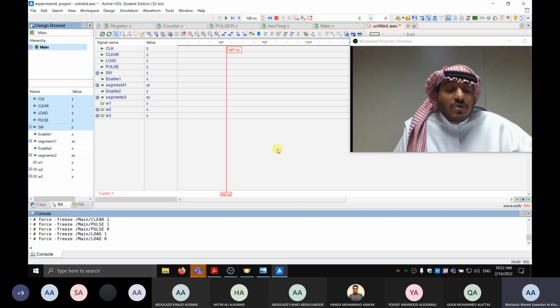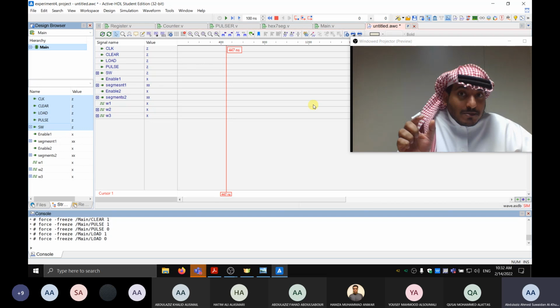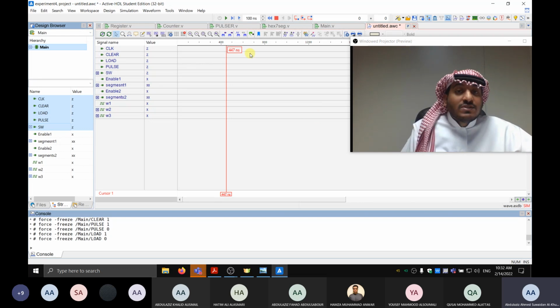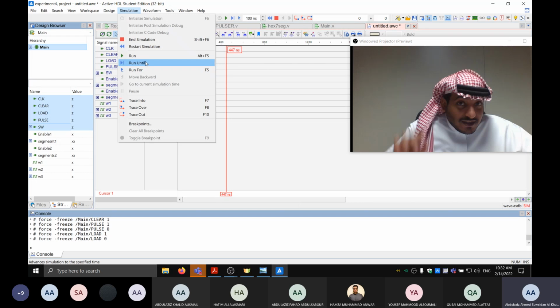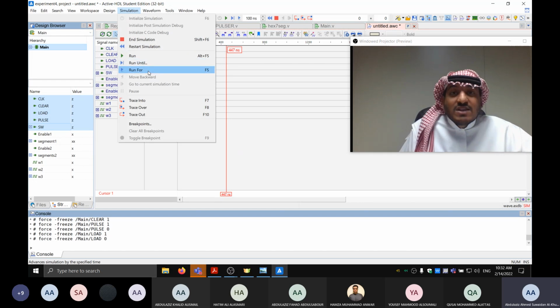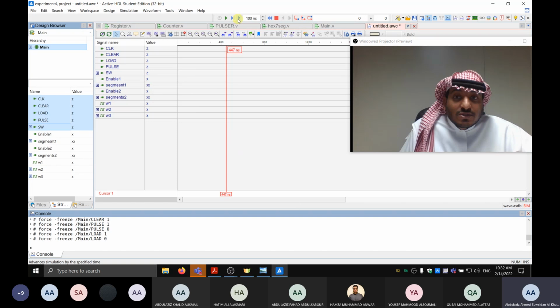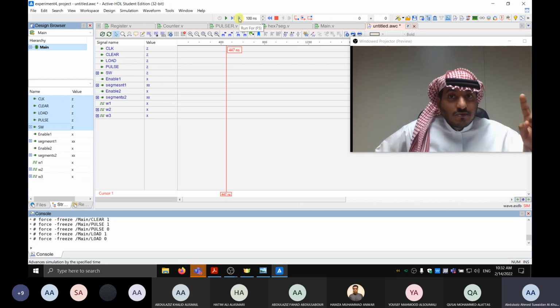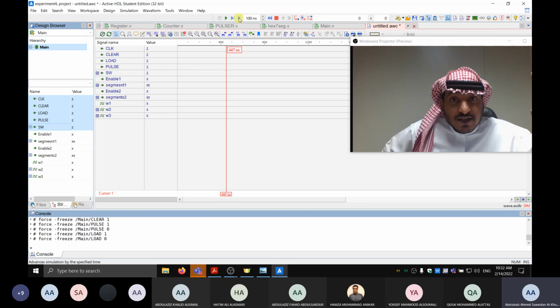Now we have to run for a certain amount of time. How to do it? You say run for. If you remember, run until the old time, and then you can say run for. You can do it from here, or there's a shortcut here. That's the same thing, run for. Don't play with it. Let's leave it at 100 seconds. So let's say run for, and let's see what's going on. The clear is working. We're supposed to see the register has a 0 on it because we cleared it.